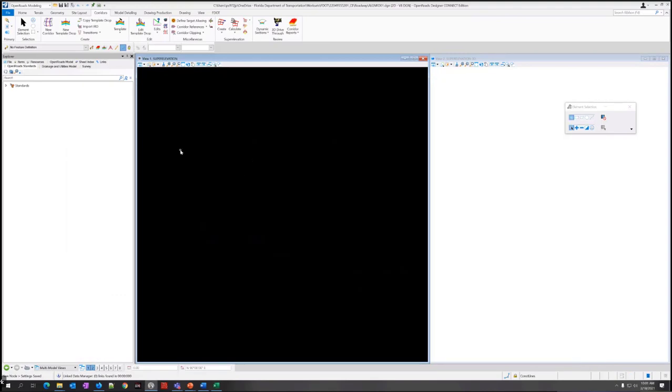And that brings us to exercise 3.2. And the first step we kind of already did here, preparing the alignment file for super elevation. We switched to the super elevation views. We set it up. You can see the 3D one already too. Just in this file, because we were working on it, it has a 3D view already created.